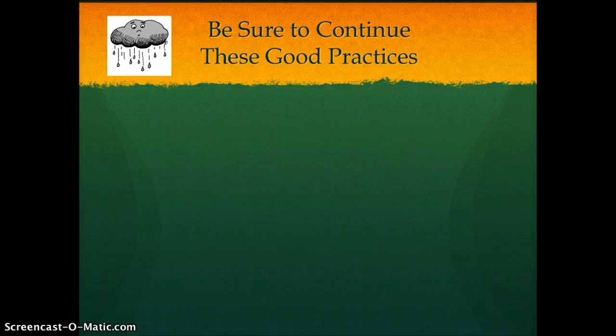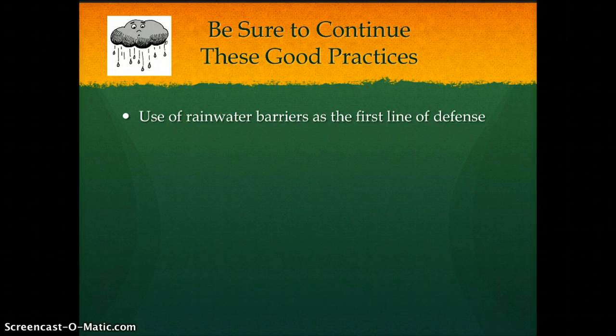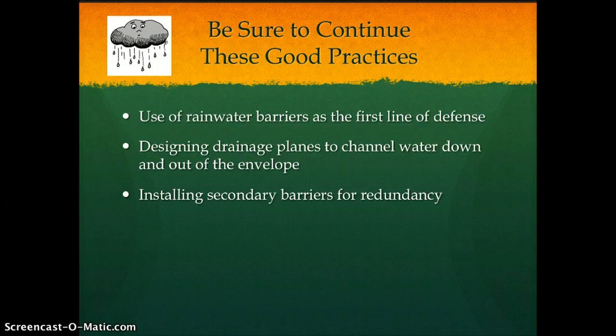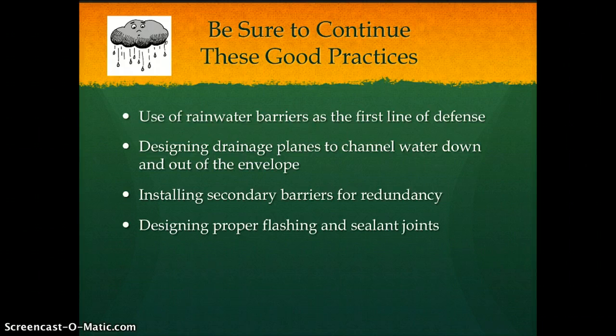are used, including implementing water-resistive barriers as the first line of defense, designing drainage planes to channel water down and out of the envelope, installing secondary barriers for redundancy, and designing proper flashing and sealant joints.